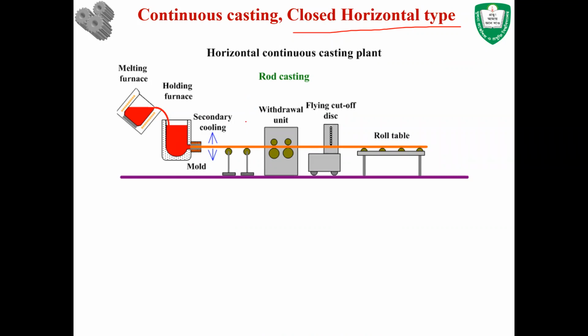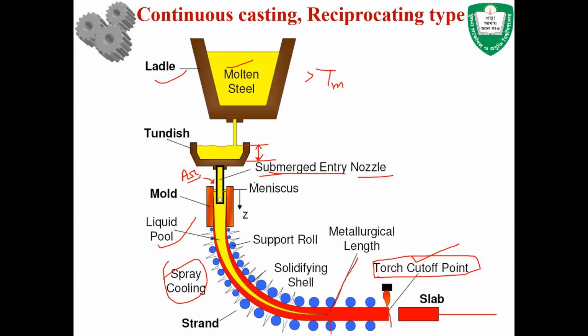And I forgot to mention another thing in this slide: the amount of material you are supplying to the mold or to the die has to be calibrated in such a way that the amount of material exiting from a certain position and the same amount of liquid placed into the mold match. Otherwise, the speed of the solid portion has to be adjusted in such a way that the amount of material that gets poured into here should not exceed.